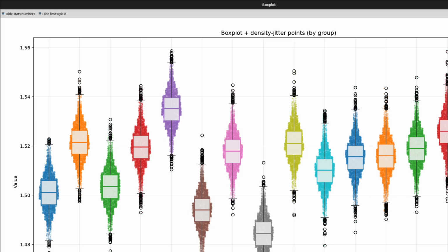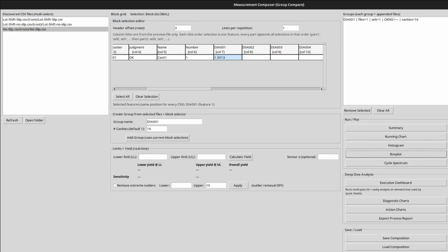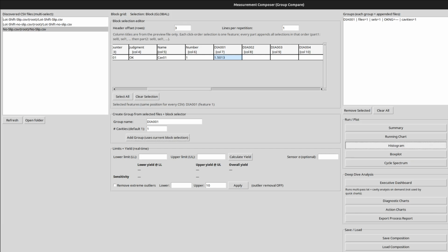It's trying to find the variations of the process, for finding if it's incoming goods or not, and then it's trying to find out if it's specific cavities so that we can select those cavities and shift them to a different position to compensate for manufacturing tolerances, so that our statistics, instead of ending up like this where everything's kind of distributed, and if we looked at this data as one, which would be what a naive look at the histogram would be.